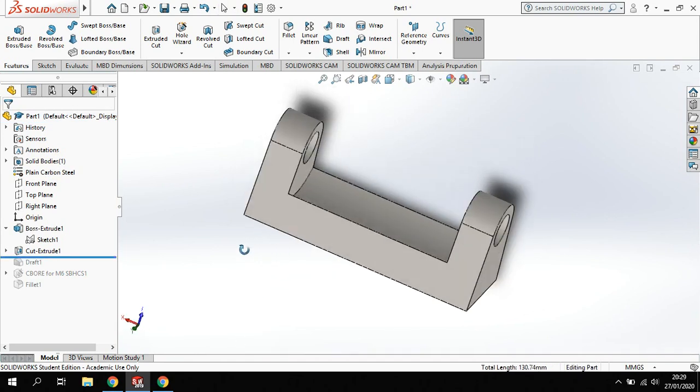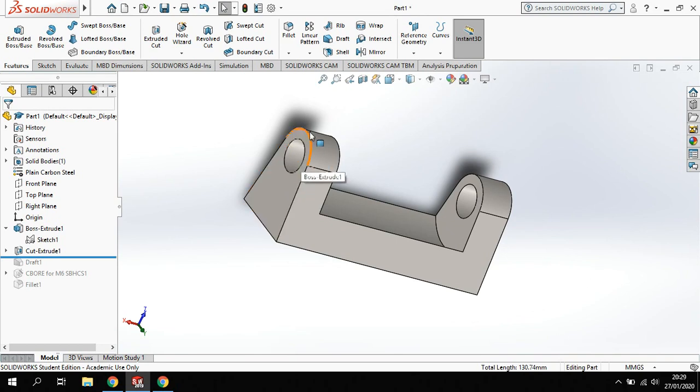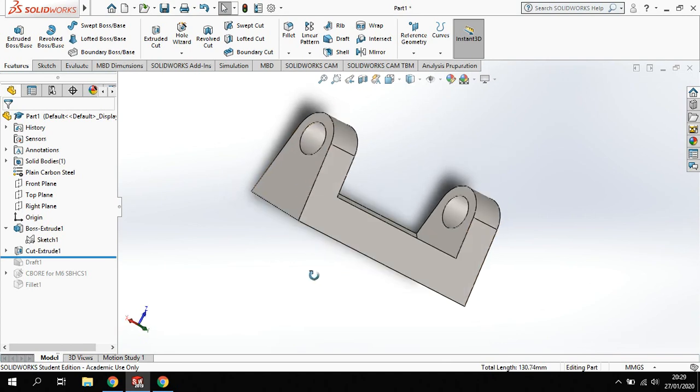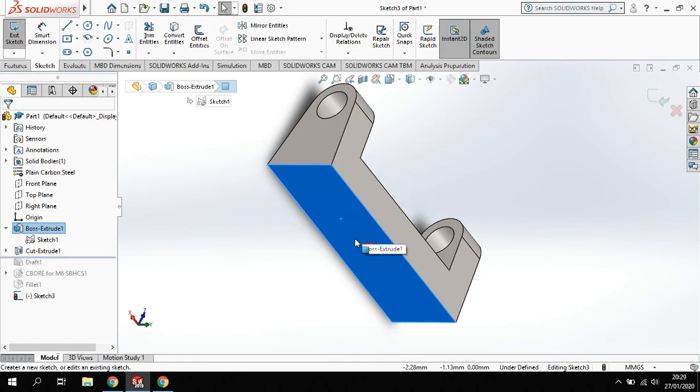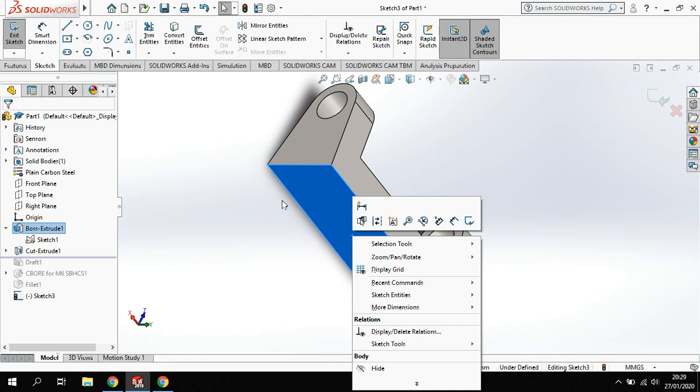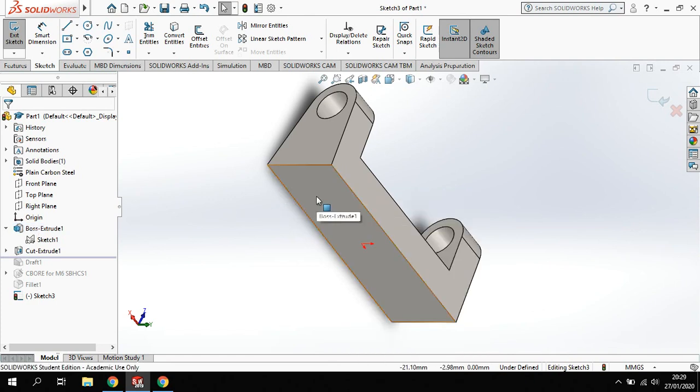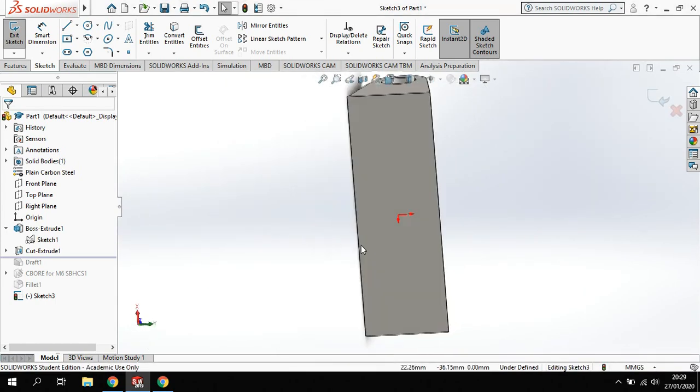As you can see now, I've got it all the way back to the point before I've got any draft angle on, and before I have any fillets on there, with all the holes for the bores and counterbores in the centre. So now I'm at that point, what I'm going to do is put a curvature on here. So going down to the bottom of the model, I'm going to sketch on there. And I am going to view that from the bottom face.